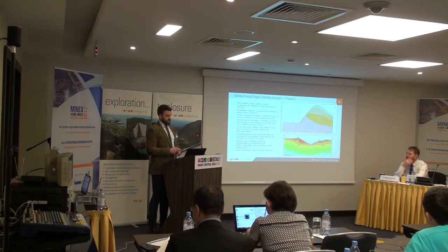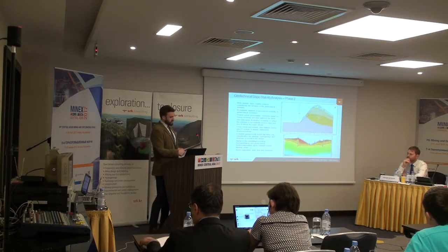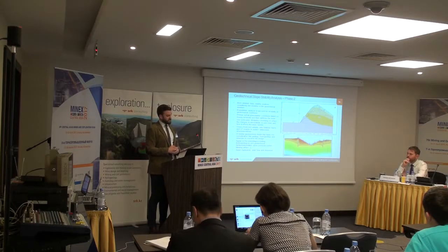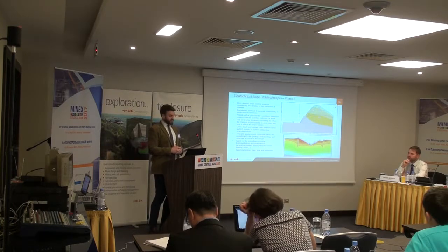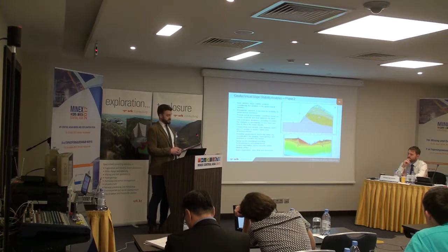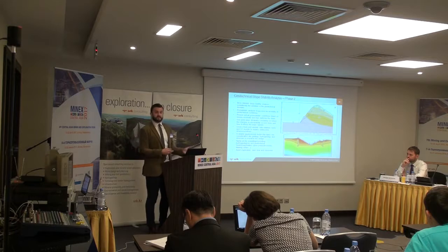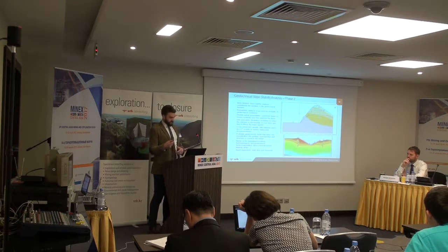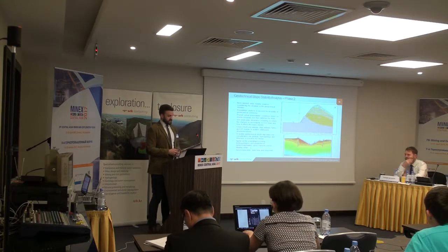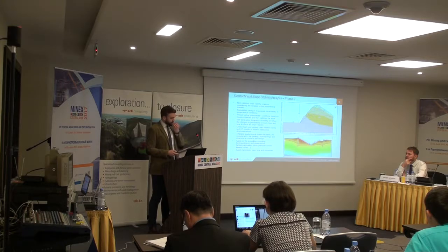And it's really here that if warranted and critical, we could use pore water dissipation modelling to reflect the changes in permeability in the rock mass and how it affects the slope stability. And it's really important that everyone works together at this stage and cross-checks and validates data between the hydro and the GT models to explain the relationship between the structure, flows and the permeability of the rock mass. And as I said earlier, a reliable geotechnical model that takes into consideration the geology, the hydrogeology and the structure is crucial to the design.